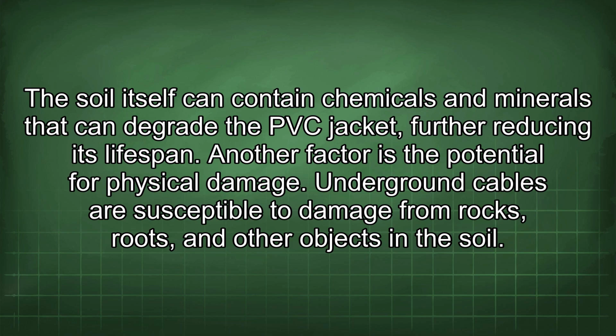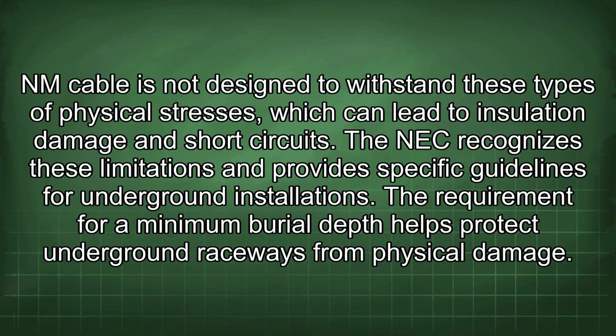Another factor is the potential for physical damage. Underground cables are susceptible to damage from rocks, roots, and other objects in the soil. NM cable is not designed to withstand these types of physical stresses, which can lead to insulation damage and short circuits.